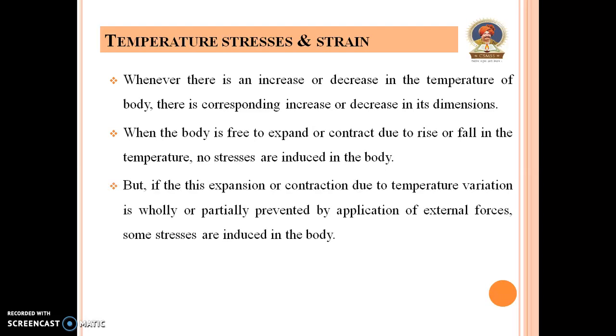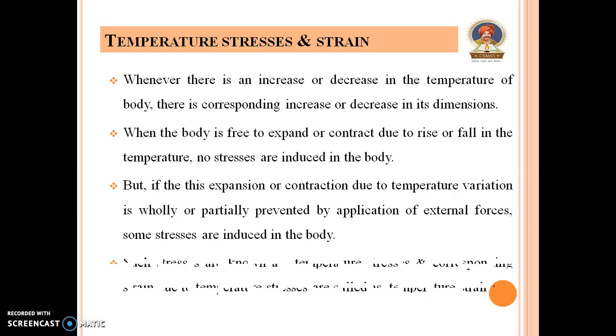But if the expansion or contraction due to temperature variation is wholly or partially prevented by application of external forces, some stresses are induced in the body. Such stresses are known as temperature stresses, and the corresponding strain is called temperature strain.